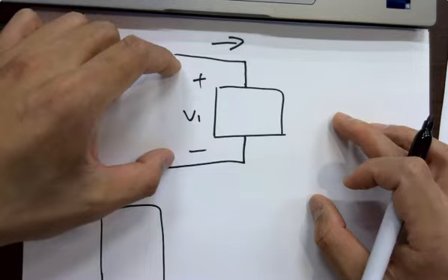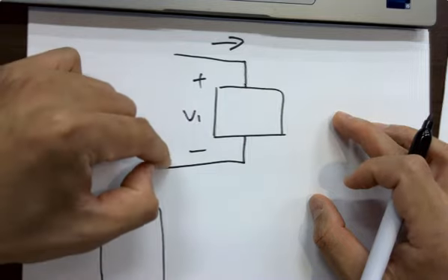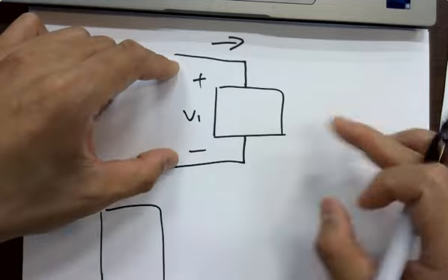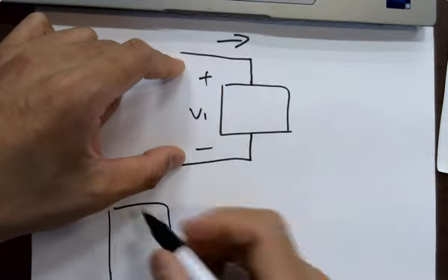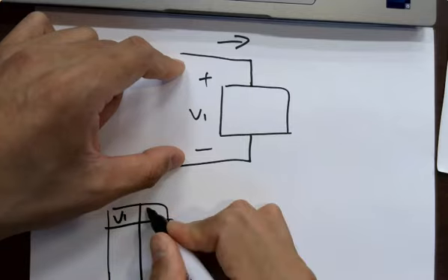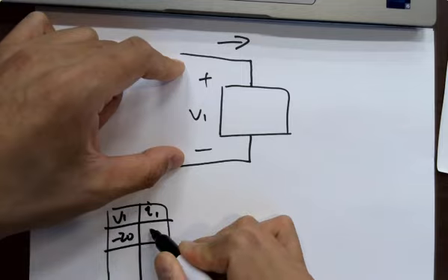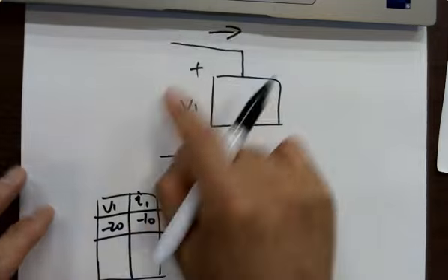If you see on the diagram a voltage labeled plus minus, do you always get a positive voltage drop from plus to minus? No. Since that's what you have seen in the table, like V1, I1, there's a number 20, minus 20 volts, minus 10 volts. So if you just apply one rule to this type of problem, you'll be fine for any other different situations. What's the rule here?